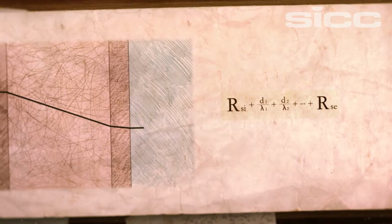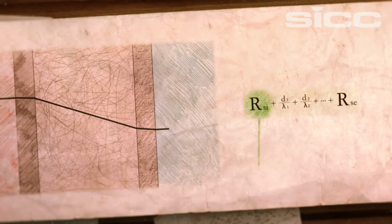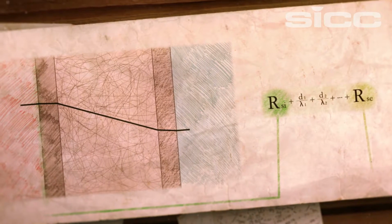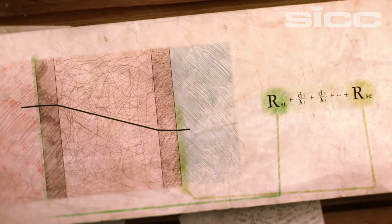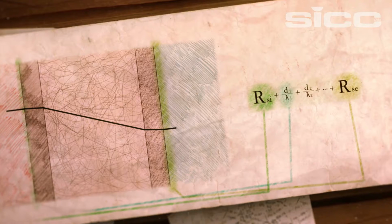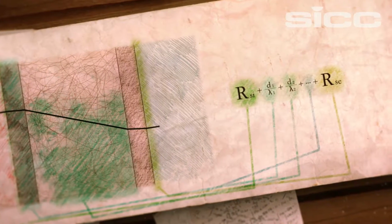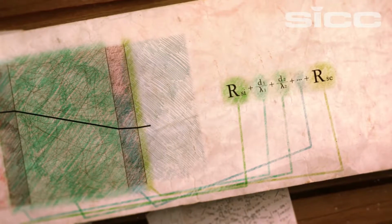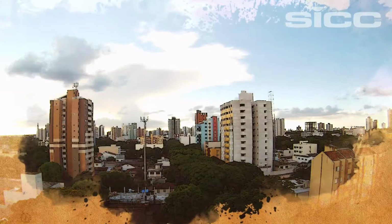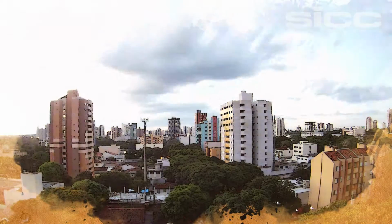This heat transfer coefficient of the wall is built up by the resistance of both inside and outside. Of course, they are DIN standardized, and they are treated as constant. The wall consists of independent layers of construction material which are specified by their thickness and value of heat conduction. For most buildings without insulation, U-values of 1.2 are known.